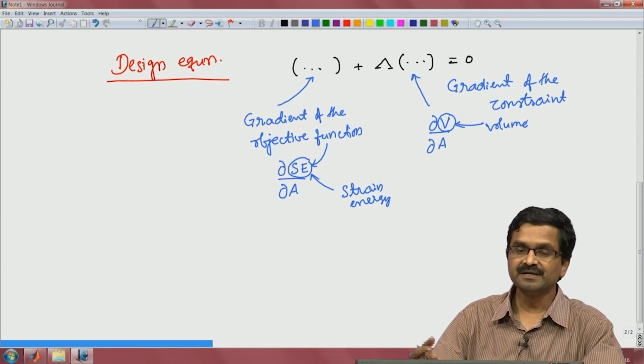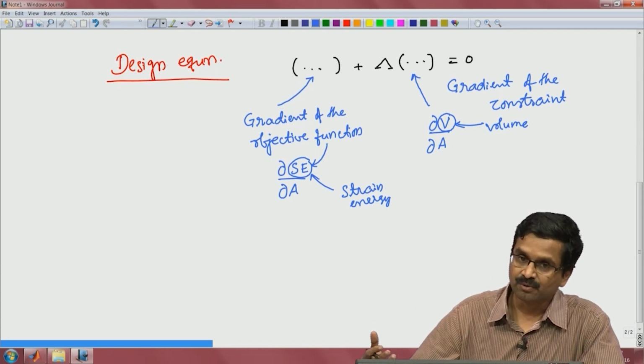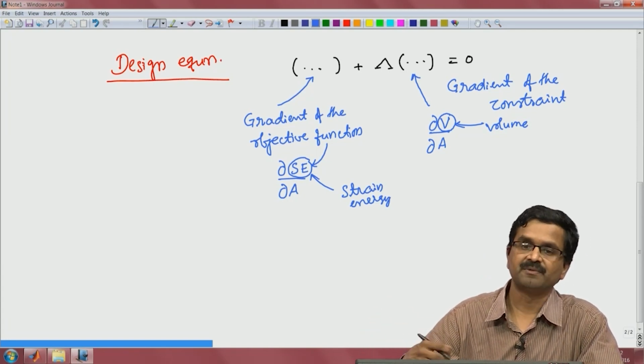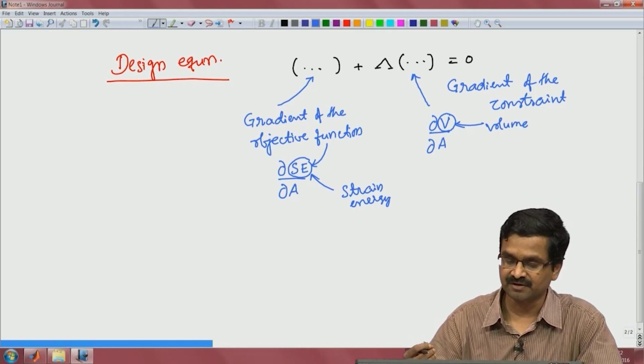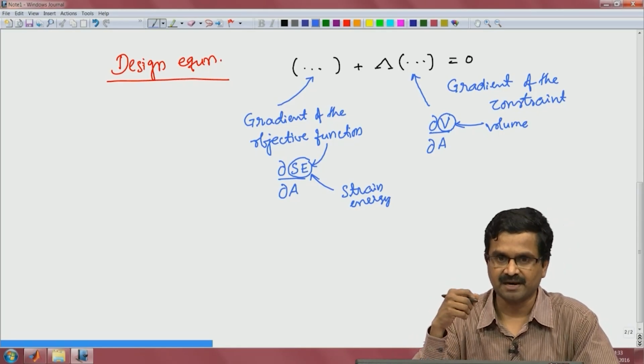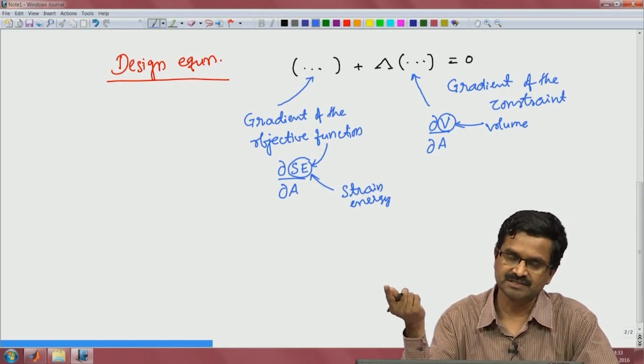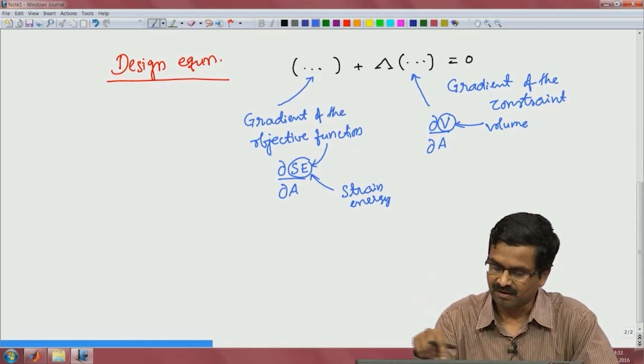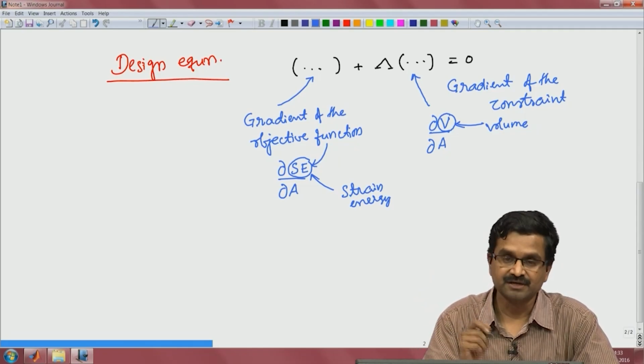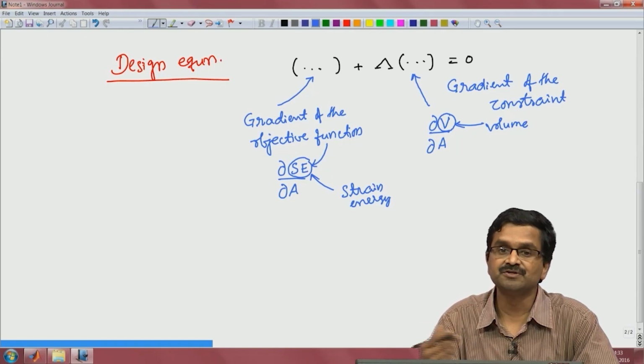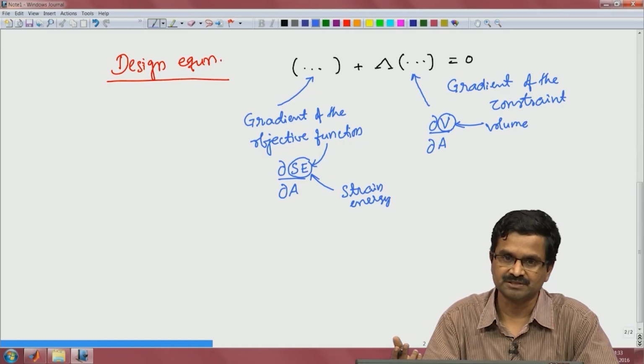Okay. And from here, by knowing that in this particular problem lambda is equal to u, that is the adjoint variable or Lagrange multiplier, lambda of x is same as u of x, we got a design equation which became simple enough to interpret, saying that strain should be constant everywhere, u prime equal to constant everywhere.